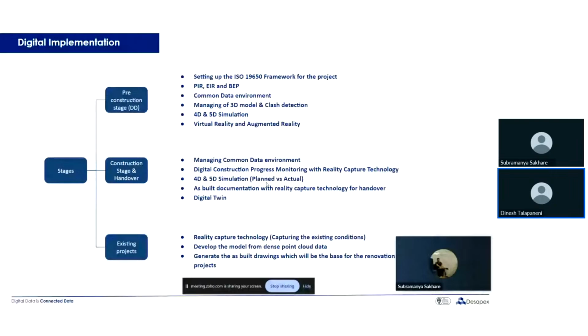And the same thing continues with the construction stage. So you set up certain things, and you need to manage those things in the construction stage as well, like managing the common data environment. And then here comes, yes, you have a schedule in place, and you need to put in some tools and technologies to bring back the construction progress monitoring using reality capture to bring back the actual work being performed on site.